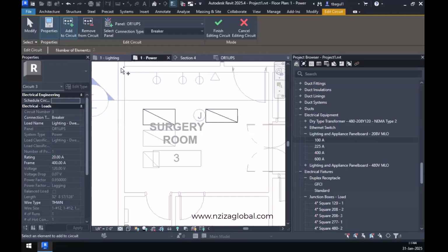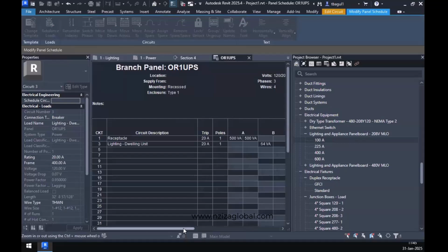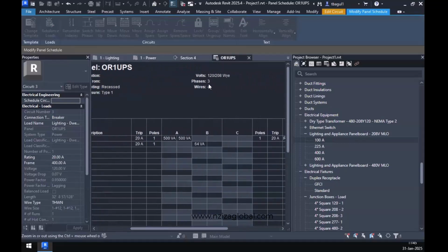All right. Now, yesterday I was trying to explain to you the difference between the tags of 2 different light fixtures, the A and B, right? In that process, I had selected 2 other light fixtures that were of other voltages, namely 277. These 2 were of 208, but these 2 were of 277. Our panel board, if you check properly, is rated for 120/208 volts.